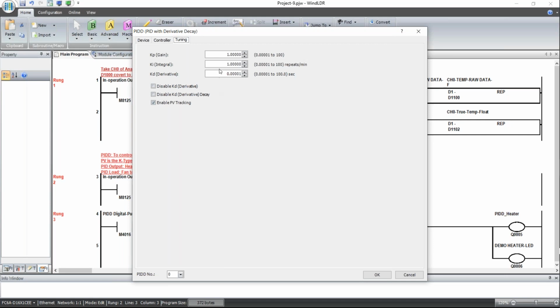And I always recommend start with small gain. I'm gonna start with 3.5, right? Why? Honestly, based on experience, this is a very reasonable number. If you go very high, you risk getting very choppy PID control, and it may overshoot in your case. And if you go very low, you risk having very small reaction.